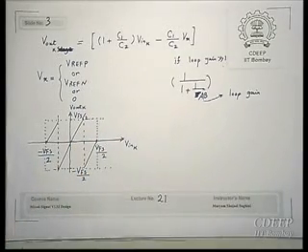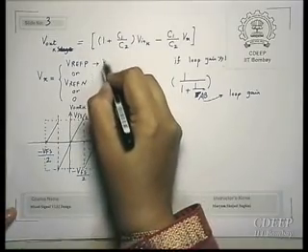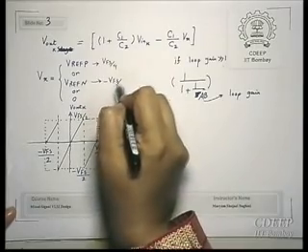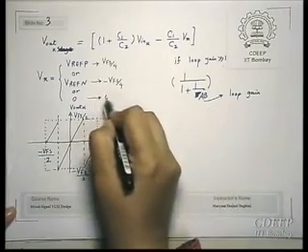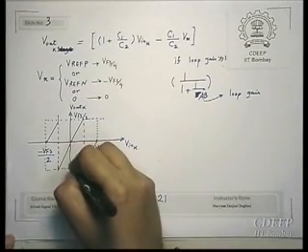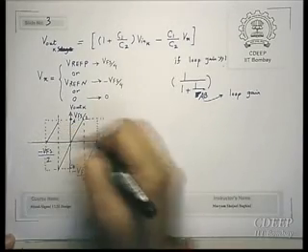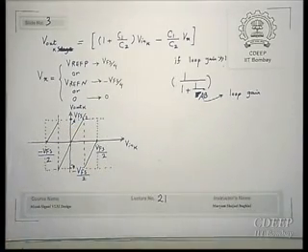Okay, this is for differential. So this Vx will be Vref P or Vref N, and Vref P and Vref N are V full scale by 4 and minus V full scale by 4, for example. This is just an example, and 0 anyway is 0. This is to clarify exactly what kind of levels are used in this particular reported work.